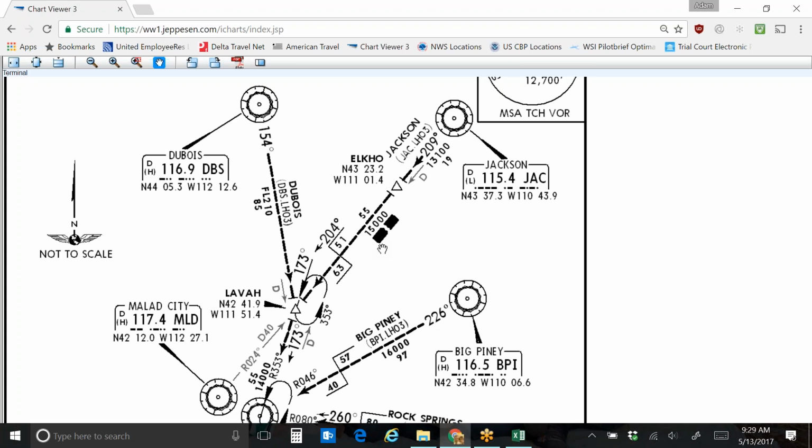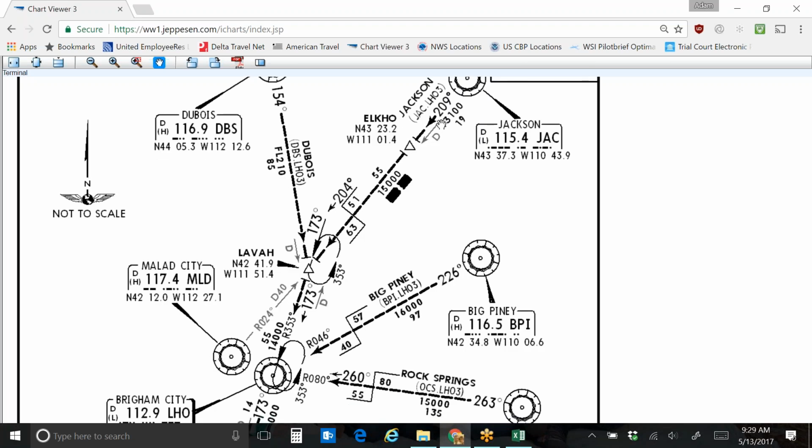So as the planes all start getting closer, ATC doesn't need to be talking to every single plane saying, okay, you descend now to 13,100, okay, you descend down to 10,000. All of those communications can go out the window, and it clears up a lot of airspace and time for them to be able to communicate more pertinent things. Because they're looking at these planes, okay, well, SkyWest here is coming in on the Brigham City 3. This Delta 260 is coming in on the Twin Falls arrival. And from any direction, you kind of get my drift, more or less what they're doing. But they are supposed to just follow the instructions, fly in, and just basically follow this route.